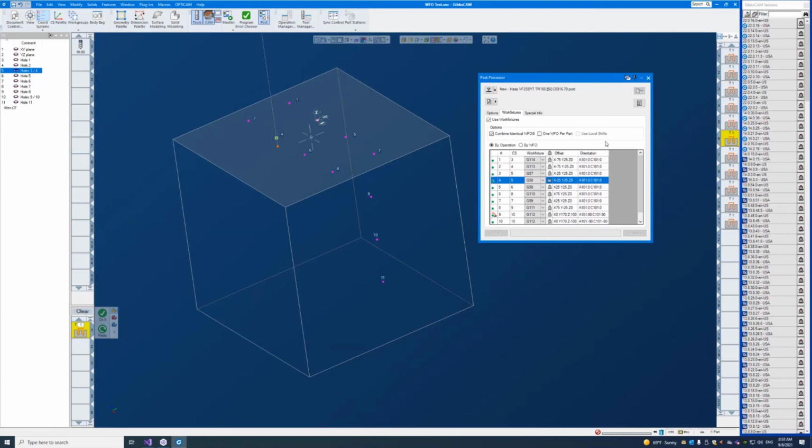It's not the way we program parts. You may be thinking that you're programming parts in that fashion, but we have to, as programmers, instruct the setup men what they're going to touch off on the part. How are they going to fixture the part? And bang, that's what makes it all run. We don't have 10 touch off locations on parts. We don't do that. We have typically one, a primary, secondary, tertiary, bang, the part's in the fixture, go.